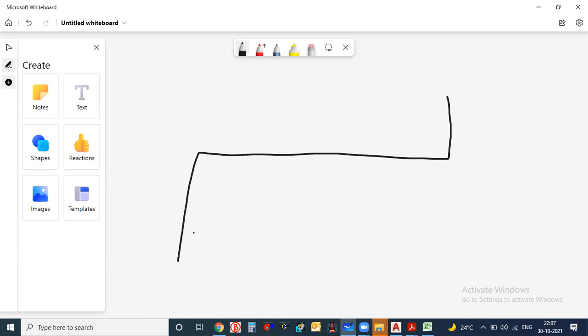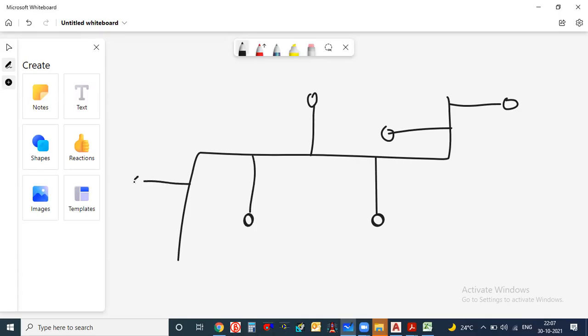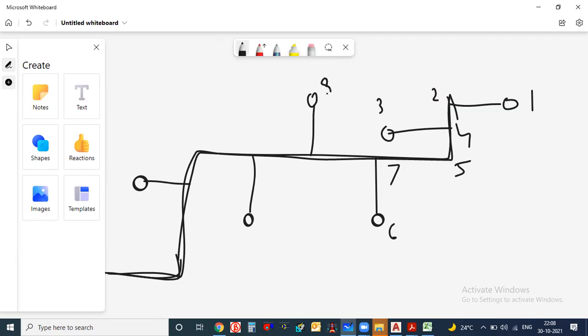And in these pipes, your sprinklers are attached. One sprinkler here. I am just showing you randomly. Now, how you are going to define the nodes means you have to follow the header pipe, or the one pipe to which all the sprinklers are attached. For example, in this case, this is my main pipe, and I want to include all the sprinklers, then what I have to do? I have to start writing the node numbers 1, 2, 3, 4, then 5, 6, 7, 8, 9.